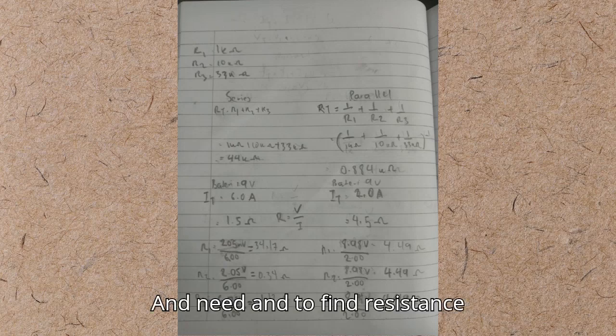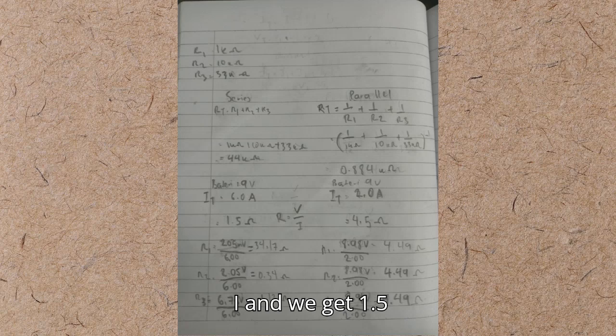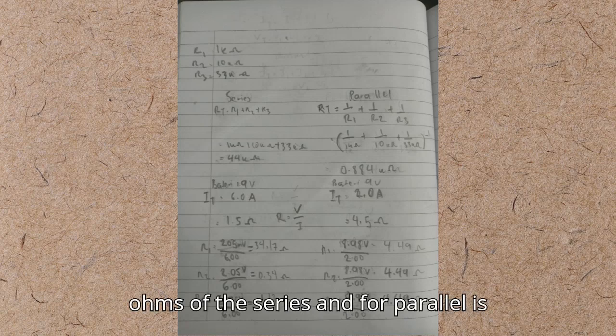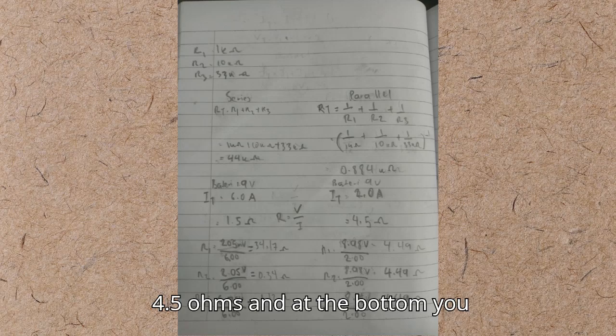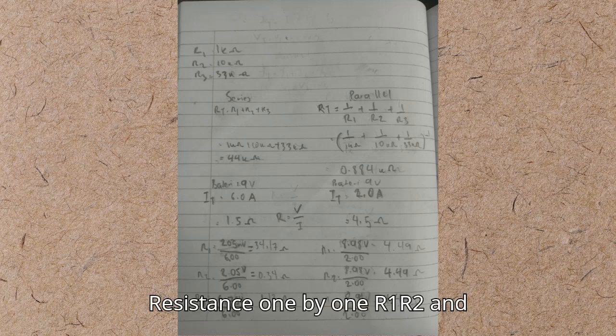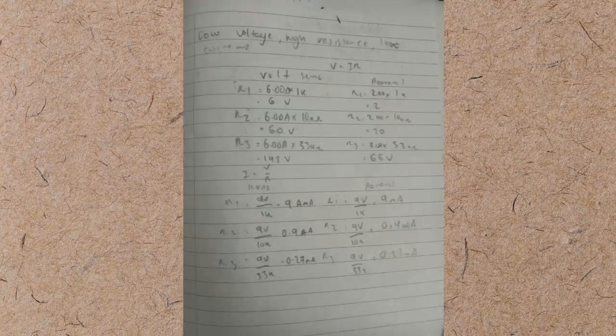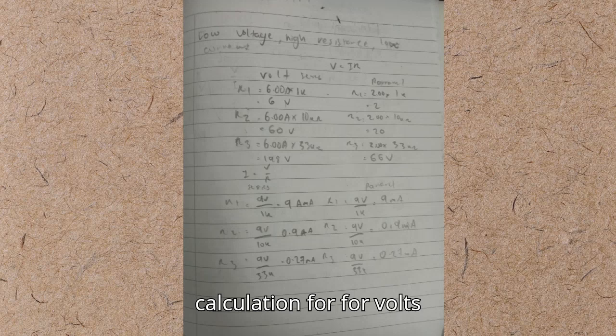And to find resistance, we need to use R equals V per I, and we get 1.5 ohms for series, and for parallel it is 4.5 ohm. And at the bottom, we can see the calculation of resistance one by one, R1, R2, and R3 for series and parallel. And the same for the calculation of volt and current for each resistor, R1, R2, and R3.